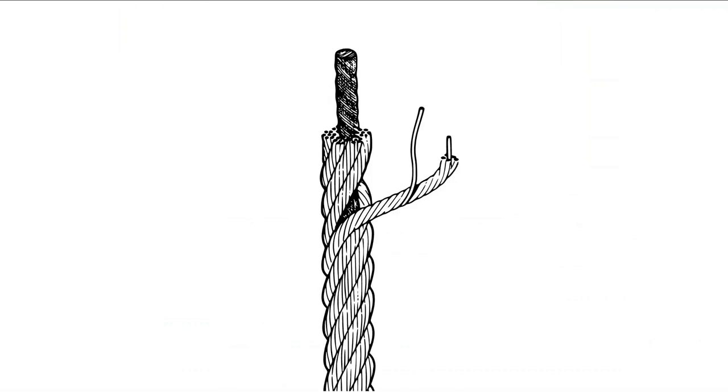We need to start first with rope. Rope is, in fact, a simple machine. It is a mechanical structure that transmits power and can control movement. Here I'm depicting a wire rope, but the principles are the same for other types of rope. Bundles of wires are twisted together to form a strand, and these strands are in turn wrapped around a central core. This provides a somewhat flexible bundle of wires that can carry a great deal of load.